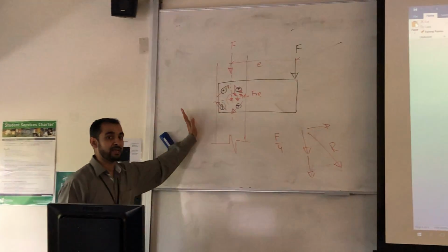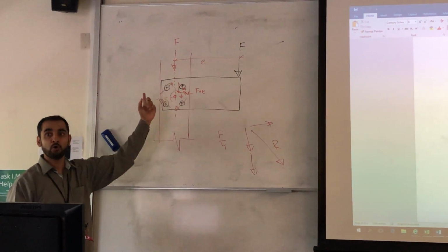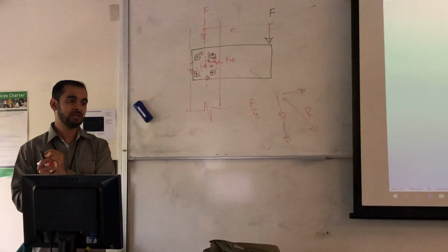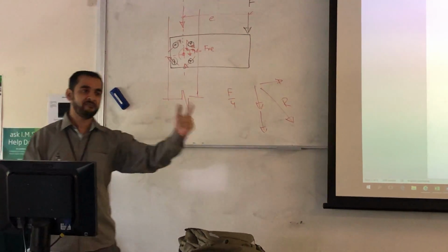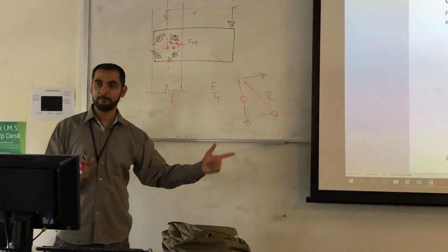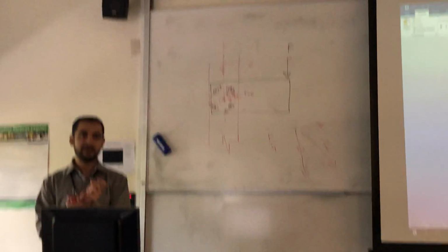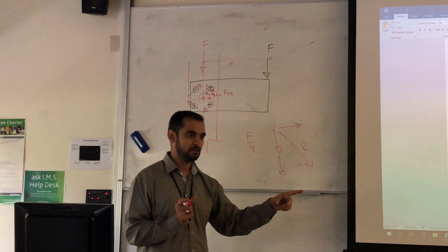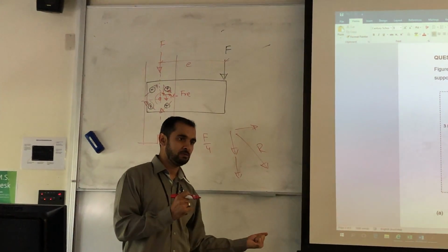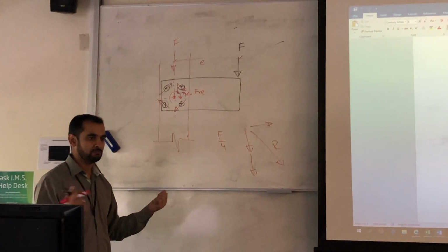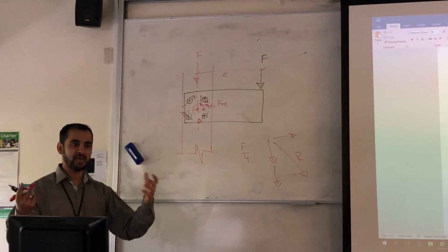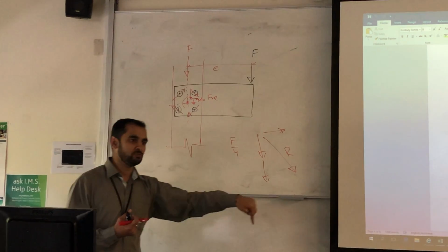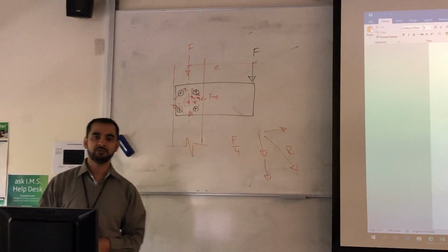So in structure, think that way: how the load will transfer, how the load will go. If we don't have a clear load path, then the load will find its own load path if we don't define it. And then what will happen? Failure. If we don't define the load path, how to transfer the loads, the load won't transfer, it's not magic. That means there is no connection, and the load will try to transfer somehow, and that's how the structure fails.